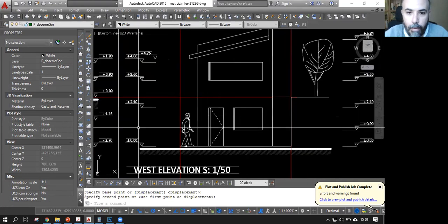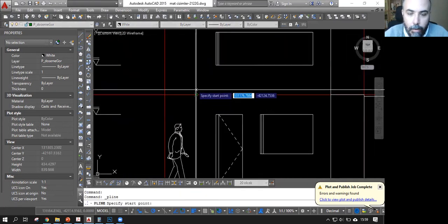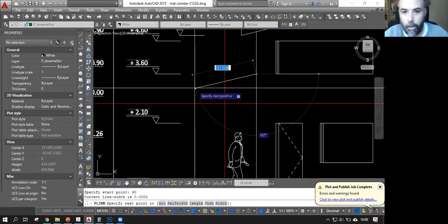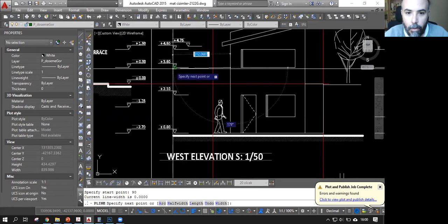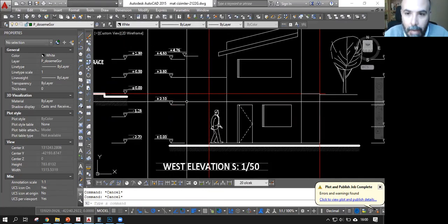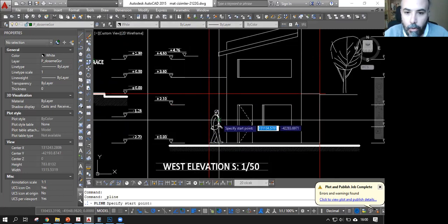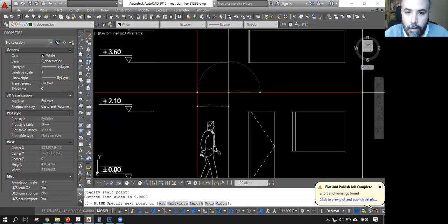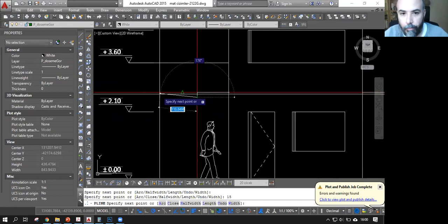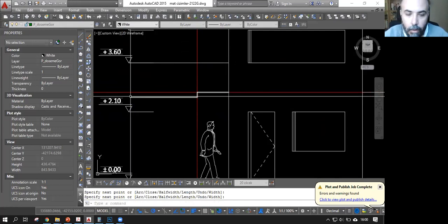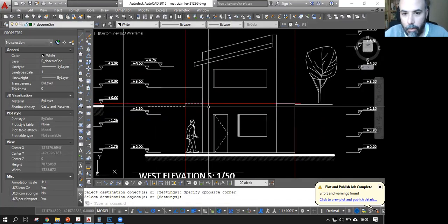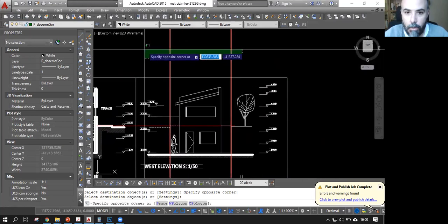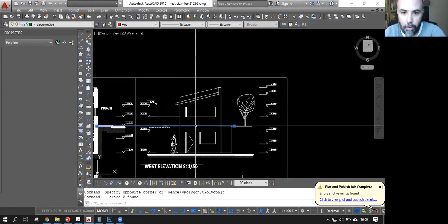And there appears the wall, and I can find the height of the wall by measuring in 90 centimeters for the parapet here, so that people cannot get hurt. And this is the level of my terrace area here, and this is the level of the, and it needs to be dashed because that's something that I cannot see itself.